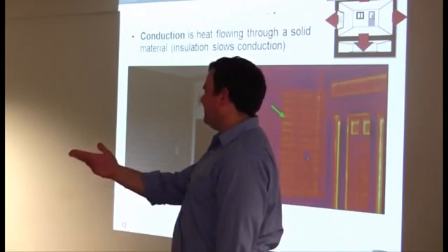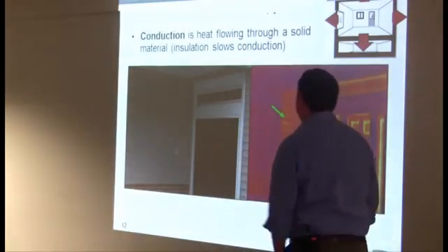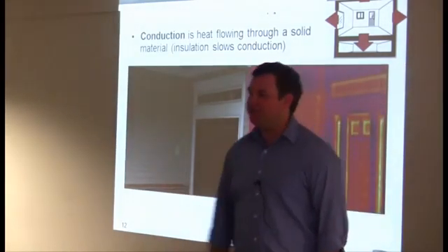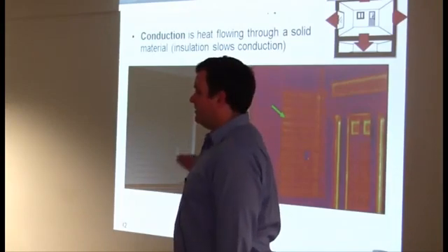That's it. Somebody right off the bat. People are usually like window, door, I don't know. We think probably a shower stall assembly went in at framing, insulation didn't get put in behind it, and you basically end up with a big thermal breach. On top of that, it's going to be a comfort issue.